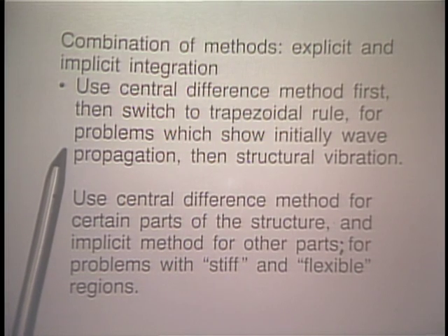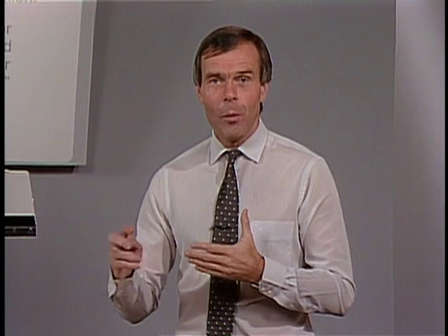In this case, you might first want to use the explicit time integration to calculate the initial wave propagation response of the structure, and then restart using an implicit time integration technique to calculate the vibrational response of the structure. So in that case, you would combine explicit and implicit time integration, first explicit and then implicit.